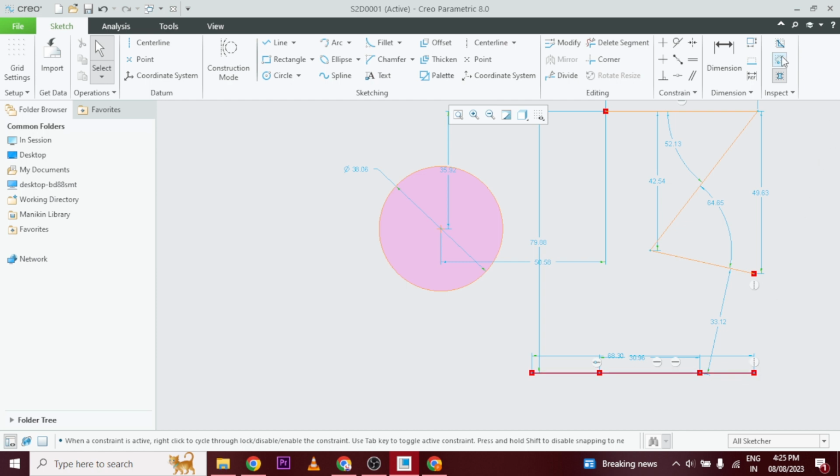And then the second option we have is highlight point ends. If you just deselect this, then whatever highlighted points are shown in red color, which are end points, will not be highlighted like this. So open ends are highlighted with this option. It will make it clear that this drawing, or you can say this sketch, is open and is not fully closed.